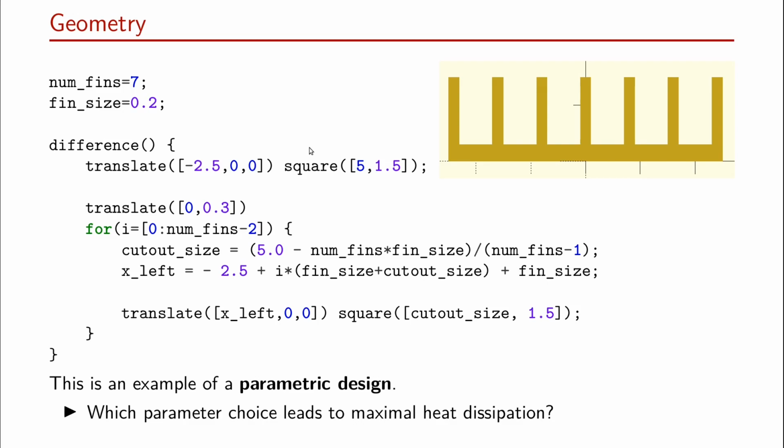Now, in order to expose the ribs, we have to cut out these air gaps in between, okay? And there OpenSCAD actually gives us a lot of possibilities to do this programmatically. So what I will do here is use a loop, okay? Loop iteration 0 will have this cutout, loop iteration 1 will have this cutout, 2 will have this one, and so on and so forth.